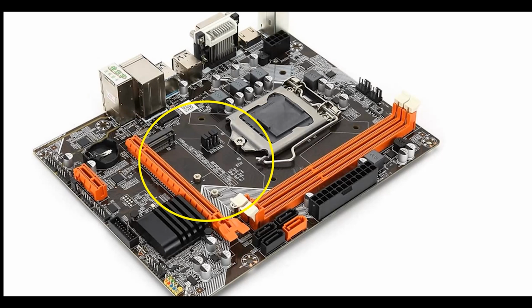You see the M-keyed socket up at the top, and then further down the board, there's space left, except for the 3 bosses sticking up to put the screw into, depending on the length of the card. It's got that notch at the top for a screw to hold it to the motherboard. When you plug this thing in, it sits at 45 degrees when you push it all the way in. And then you have to push it down so that all the connections are pressed in. And to hold it in position, you put a wee screw onto one of these things.